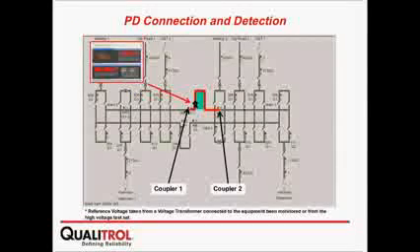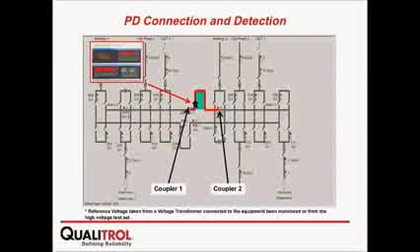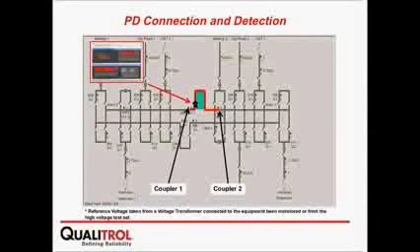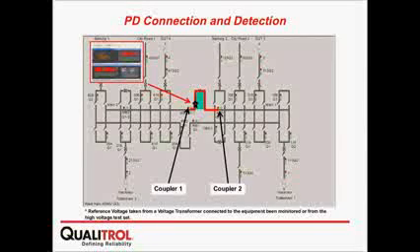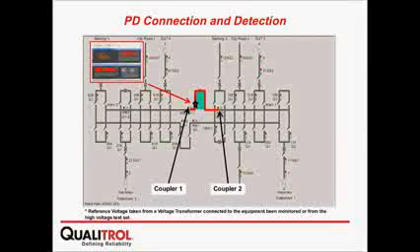What you see in this slide is two coupler locations at the bus interconnect. If you have a partial discharge event at the location of the star, using a monitoring system you can calculate the location using the time of flight from the two couplers, coupler 1 and coupler 2, and hopefully characterize accurately what kind of partial discharge event that is and prevent catastrophic damage in your system.